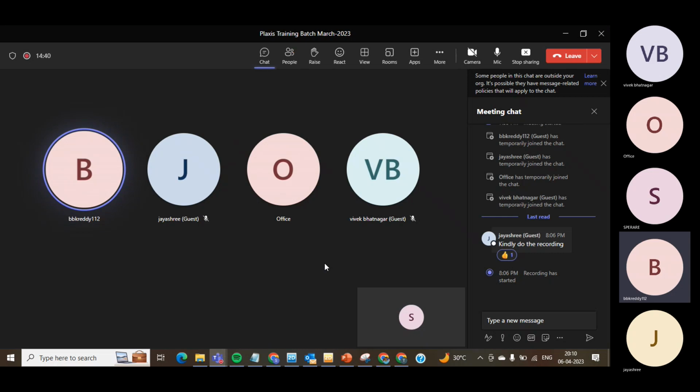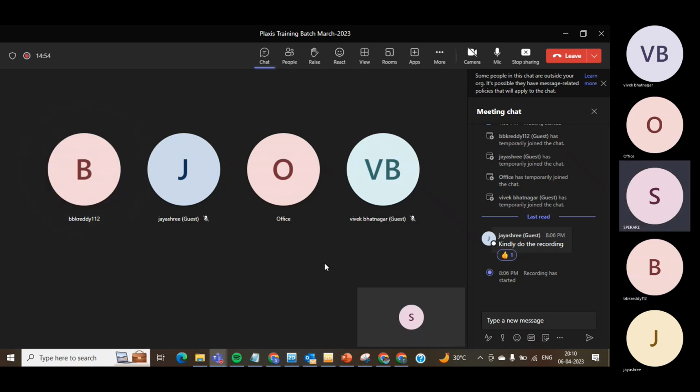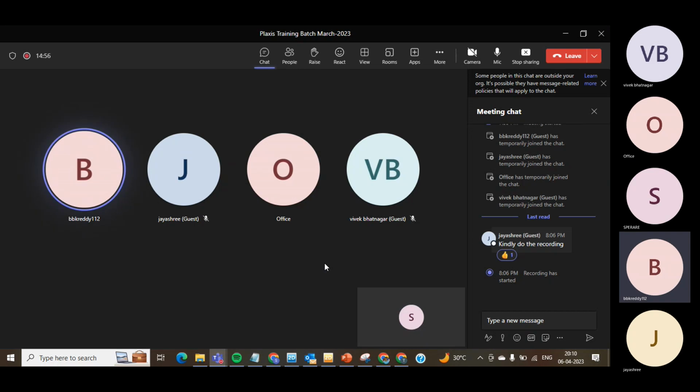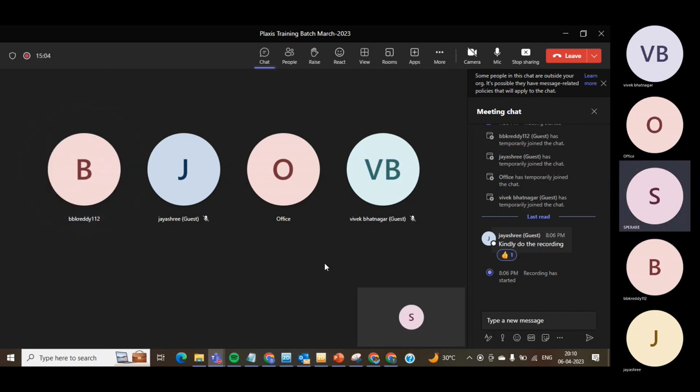I have one more doubt. How can I calculate the total settlement that happened? Because I incremented the load in 3 stages, but in each condition it shows different deformations. Is that for that particular load? We are going to cover that in the Plaxis viewer part, which we have not yet come across. I'll tell you how to see phase-wise displacement and incremental displacement.